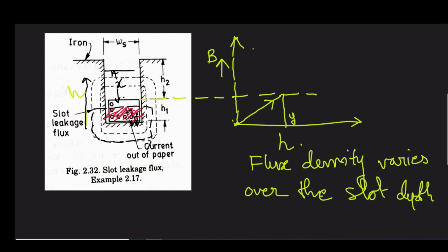And if you are apprehensive of considering all this elite mathematical consideration, you can just apply your common sense and intuitively understand that if we enclose a small amount of current here, then the amount of H will also be small, and as we move up, as we start covering more cross-sectional area of the conductor, we will be able to enclose more current, and that will increase the H.